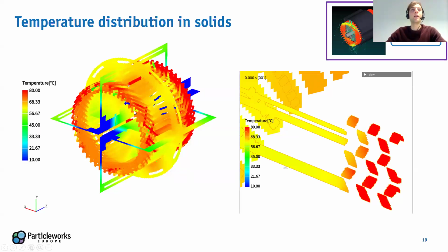We can see that we applied basically the cooling maps on the coils and on the other elements. We applied power losses to the model, and then the electromagnetic losses that were estimated with, let's say, an electromagnetic software. And then you can see again the cooling effects of the jets and the most critical areas, okay?